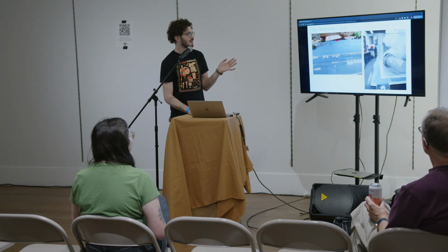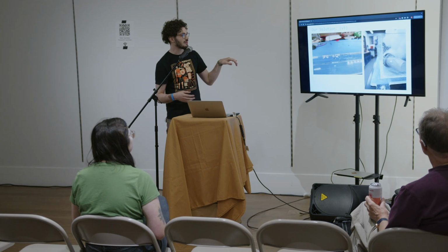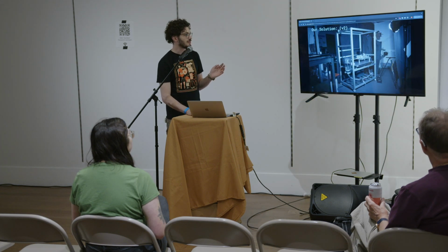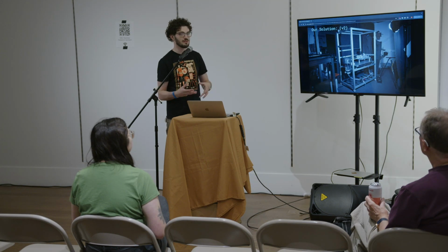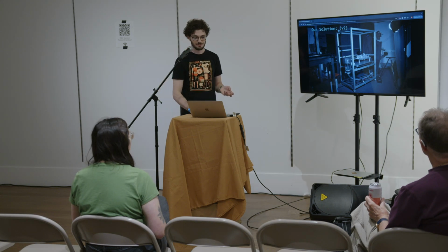Here are some examples of this long-term loading. The water's heavy, it's a big span, and these little cracks that form on the edges of the acrylic because of heat stress put into the material during laser cutting slowly propagate over time. And this was just a constant problem. So for the second version, we started from scratch and tried to design something that other labs could hopefully use for a longer time, something that'd be more reliable, more stable, but still reproducible.